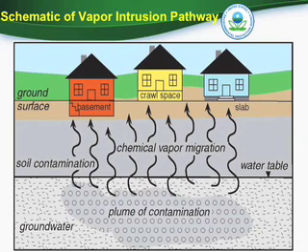So here's a schematic, or cartoon, of the vapor intrusion pathway. If we have contamination here in the subsurface, it could be groundwater, it volatilizes and then migrates. It's not a straight little path, but it migrates through the subsurface soil gas and potentially enters into the different types of foundations. Here it's showing residences with the different types of foundation, a basement, a crawl space, or a concrete slab foundation. So there's the potential for this, and then also into non-residential commercial buildings as well.